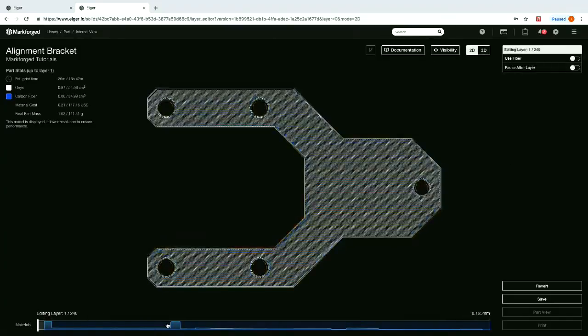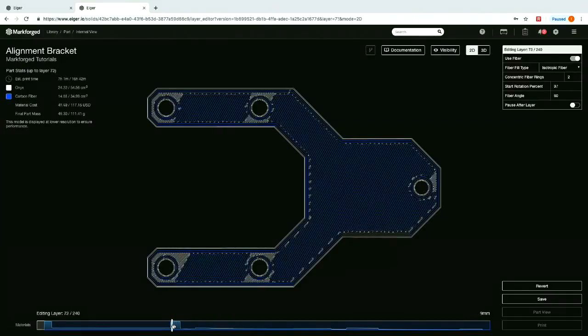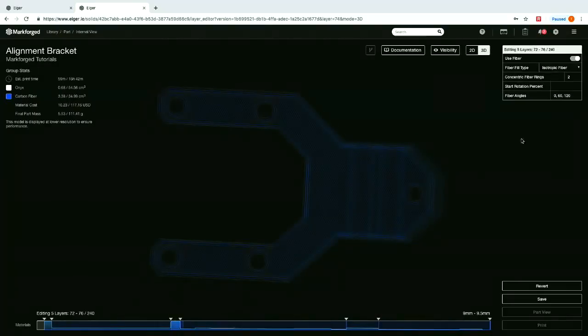So if you go in here now and we look at this fiber, instead of doing 45, 90, 135, 180, which is a 4-step kind of spin, now it's doing a 3-step spin. That's something you can do dynamically. You can also go into the same thing and say you want a lot of fiber oriented in the same way. I could just make it 0. Or if I was feeling special, I could make it like 56 with some random number. And the fiber will orient based on the cardinal direction the STL is oriented as.